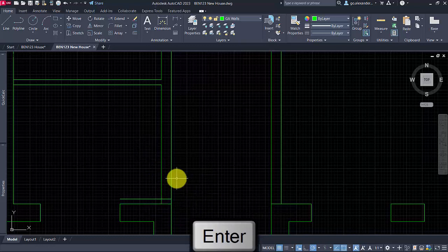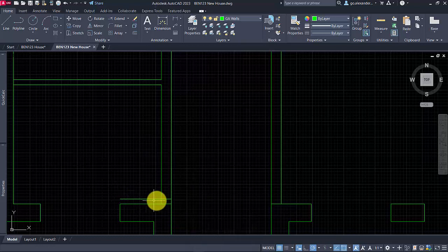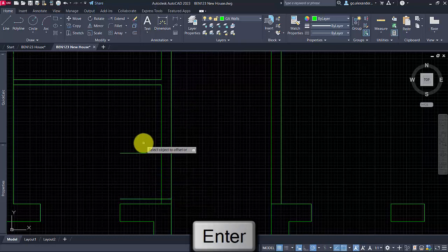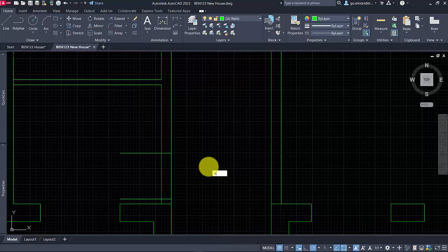So when you imagine a door opening, if the door opens to the position where this line is here, when the door opens, you don't want the handle to hit off the wall or hit off a window or anything like that. It's best to have a little bit of a gap in behind there. That allows space for the architrave and so on around the door also. So offset 910 also gives the opportunity to put a little bit of a door stop in there just so the door handle doesn't mark the wall or whatever.